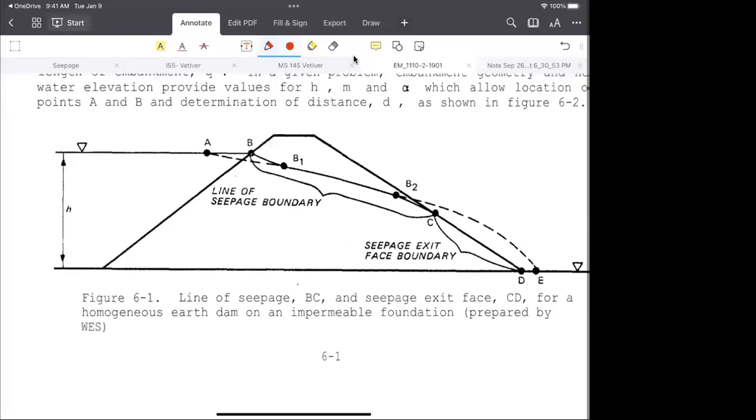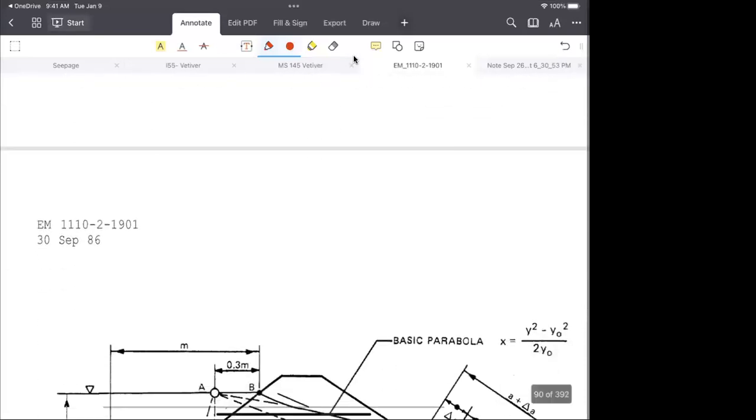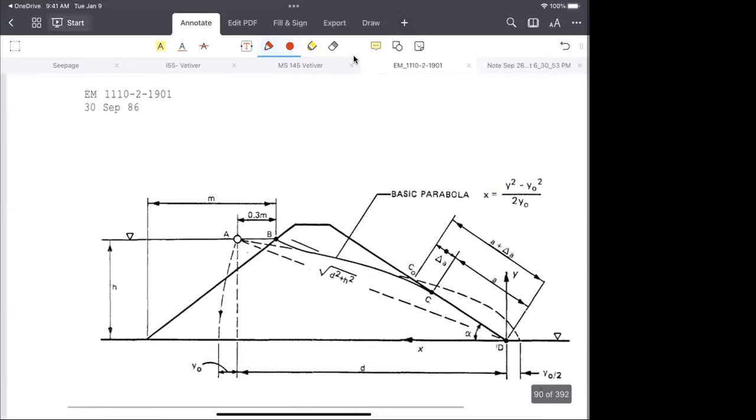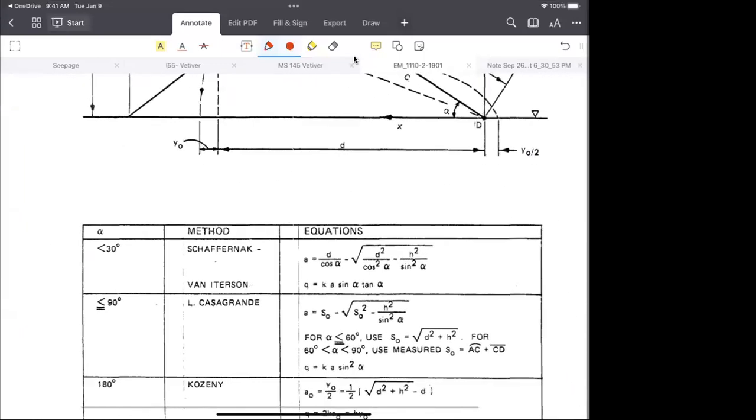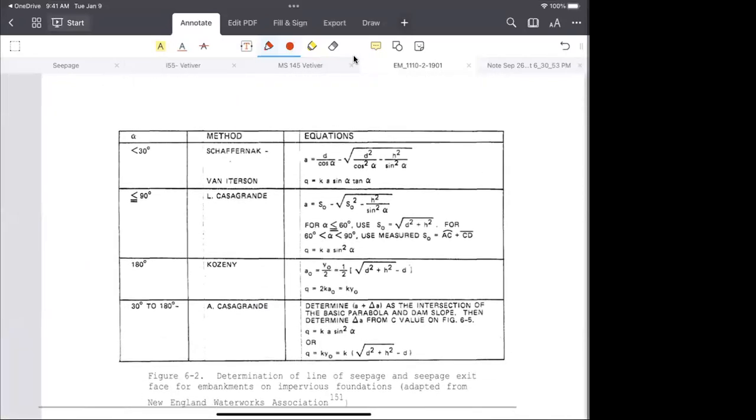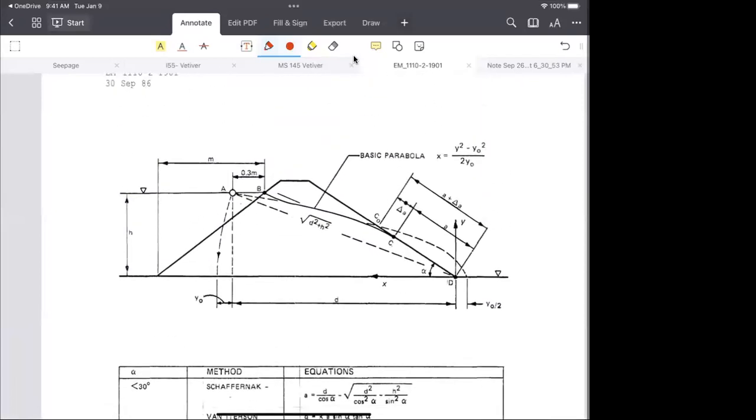Okay, very good, excellent. And then we just need to follow the regular way of how we draw the flow net. All of our equipotential lines are drawn perpendicular to our flow lines. And we need to find out what is the top and the bottom one, and it goes like that. So that is the graphical way of developing the flow net. But the first thing is we need to learn how to draw the flow net.